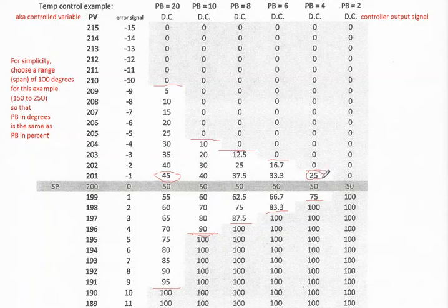The controller signal will drop more drastically, all the way to 25%. It was at 50%, maintaining your set point. The process variable went over temp. The output signal reacted pretty drastically. It cuts the signal all the way down to 25% when it was sitting at 50.